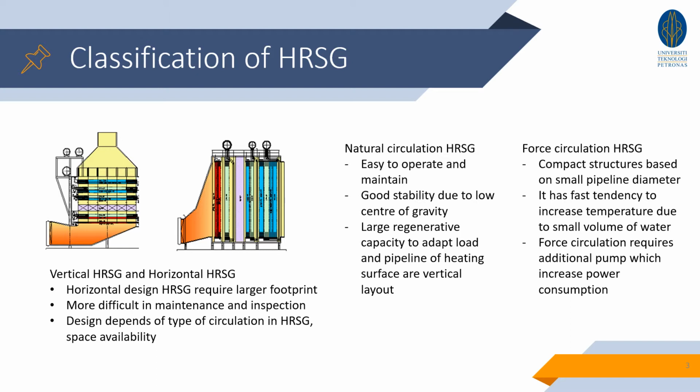Horizontal design HRSG requires a large footprint. It is more difficult in maintenance and inspection. The design of circulation in HRSG is highly dependent on its orientation, which is determined by the space availability.